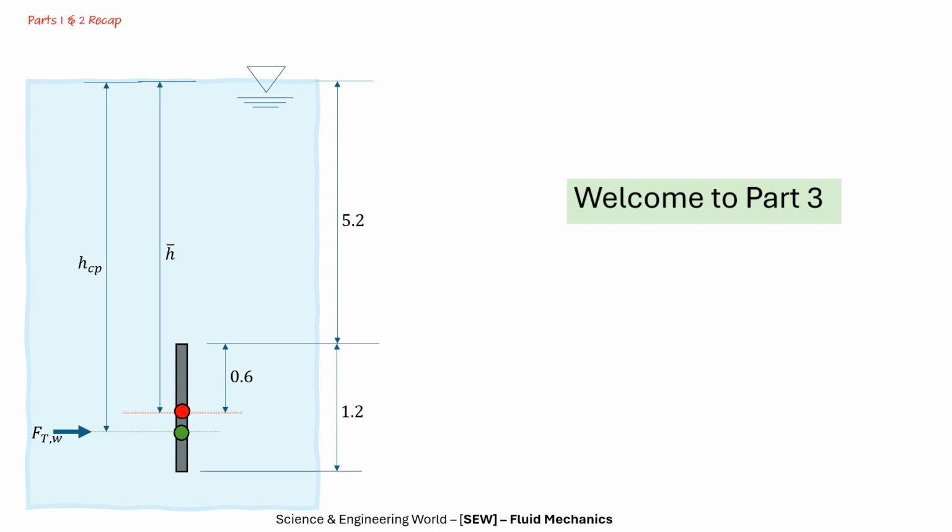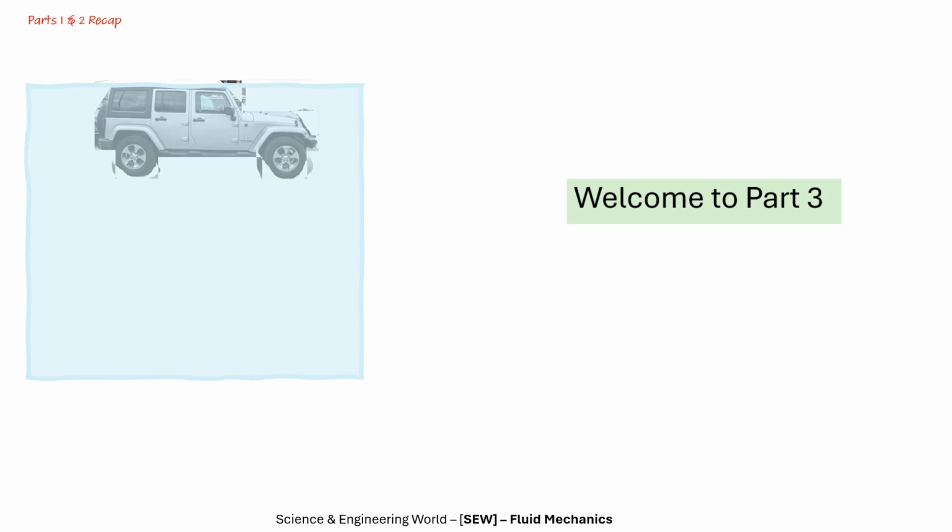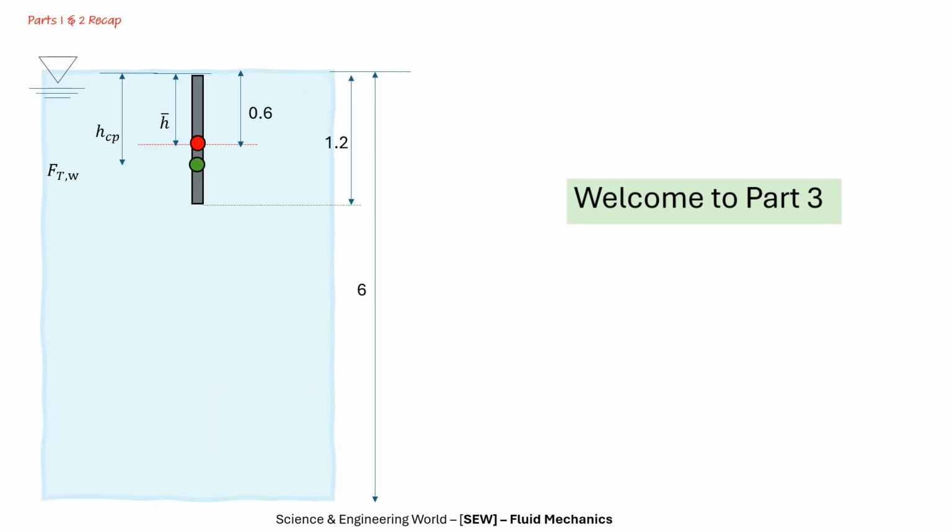And then we went further to see if he could escape if the top of the door is at the level of the water. Here we also established that the water was exerting a force of 8 kilonewton on the door from outside, and the driver was exerting his 1 kilonewton on the inside. Again, we found out that it's not possible for the driver to escape here with his own effort of just 1 kilonewton.